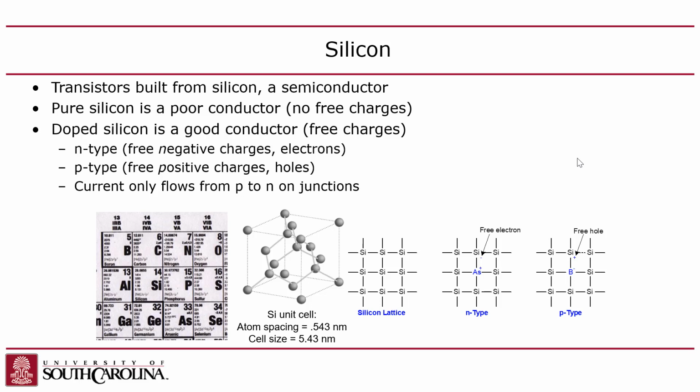And so this thing starts to conduct current, right? On the other hand, if you reverse bias it, meaning you just switch the voltage, so you put a positive here and negative here, the charge carriers move away from the junction, and it creates an area where there are no charge carriers. And so it blocks the current. The current won't flow backwards, right?